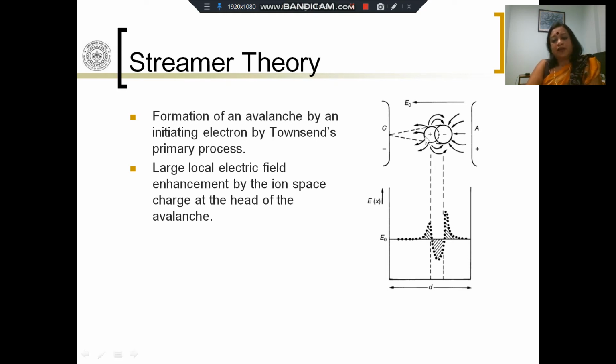So what will happen is, at some point we have a situation where, let's say, most of the collisions are concentrated in this region, and there is a positive charge center. Because the positive ions have not been able to move completely towards the cathode, in this cone there are a reducing number of positive ions. A few have reached, a few more trailing here, a few more trailing here, most of them located here. Same with the electrons, most of them have already reached the anode, but some are still there and trailing, and they are ahead of the cathode, and this whole thing is towards the cathode.